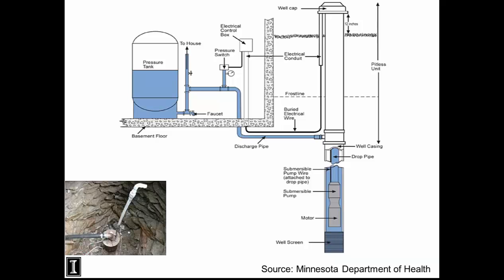And so your pressure tank is set to run at usually a maximum and a minimum pressure so that you have enough water pressure in your house. And when you fill the tank up until the pressure switch reaches a certain high pressure, let's say 50 psi, that means there's some storage of water in the pressure tank, and it pushes water through your house whenever you turn on a faucet. When that gets low enough, the pressure switch gets down to, say, 30 psi. This is an example. Some are set 40-60, 30-50. It just depends on your area and what you need.